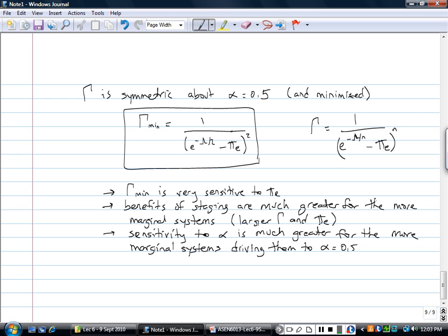So everything is just reading those curves. If we have anything more than a really good empty mass of 35%, these curves are not really working to our favor at all. 35% and lower, if we could get lower, things are flattening out where you can pick your energy split maybe more advantageously than where the energy is providing, but maybe something that's more advantageous for your recovery of a first stage or whatever else you might want to try to do.